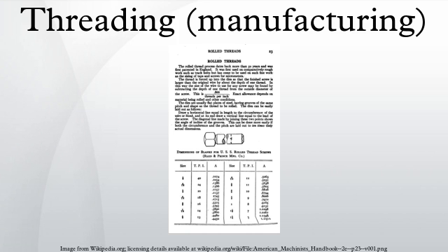Note that the tap drill size differs from that used for a cutting tap and that an accurate hole size is required because a slightly undersized hole can break the tap. Proper lubrication is essential because of the frictional forces involved, therefore a lubricating oil is used instead of cutting oil. When considering the blank diameter tolerance, a change in blank diameter will affect the major diameter by an approximate ratio of 3 to 1. Production rates are usually 3 to 5 times faster than thread cutting.